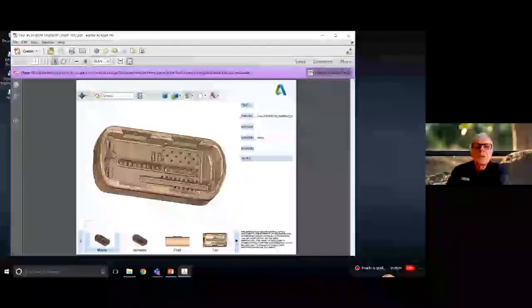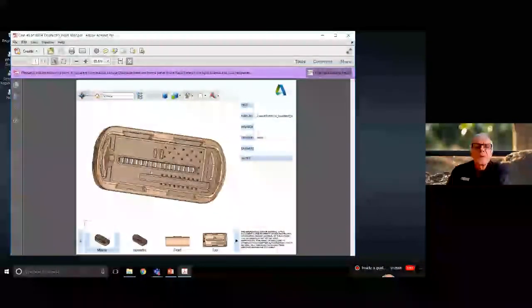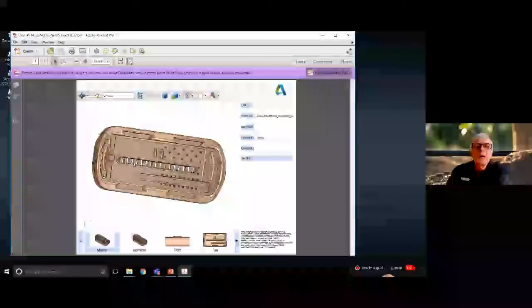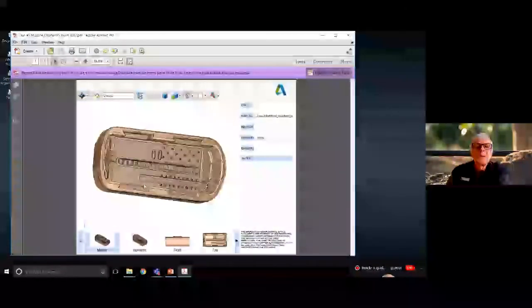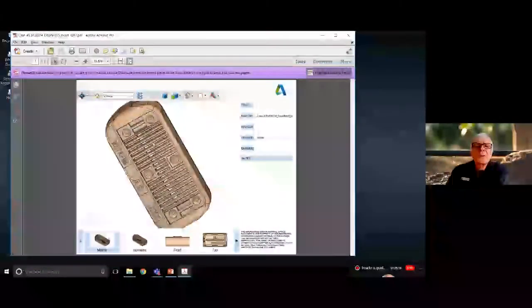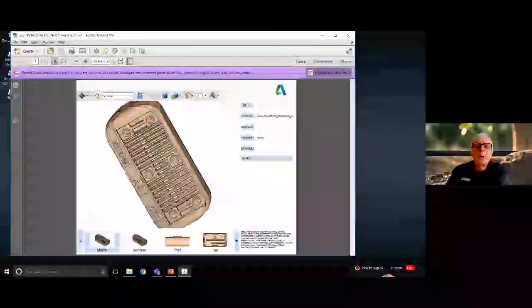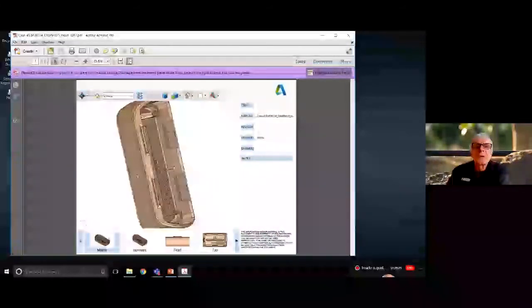Now if we look at a similar one, this is a DripNet PC dripper. This is part of the inside of the dripper, and that's the inlet. The diaphragm actually rests against here. And then if we turn that over, you can see that each one of these slots is connected to the inlet. The diameter of these slots is obviously less than the inlet diameter and less than the flow path diameter of the actual dripper.